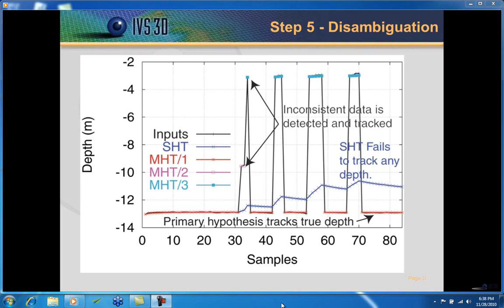You have one which is a neighborhood, so it looks in the neighboring soundings cells, and whichever one of these values here is most consistent with the neighboring one is selected. You also have a combination of the number of samples and the neighborhood, and then there's a predicted surface or average surface, and whichever one is closest to that average is used as well.